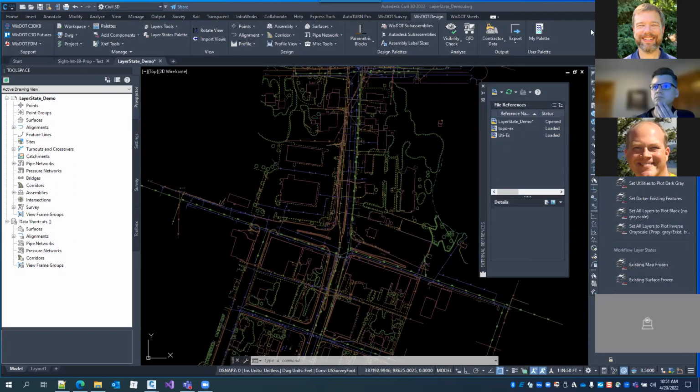And you could use it anytime you're trying to do obstruction. Obviously intersection is the big one, but also sitting at a roundabout, seeing what you could see, or anytime that you get into a bridge parapet or any kind of visual obstruction, this would work. Decision point, path, set up your surface, set up your obstructions, right?